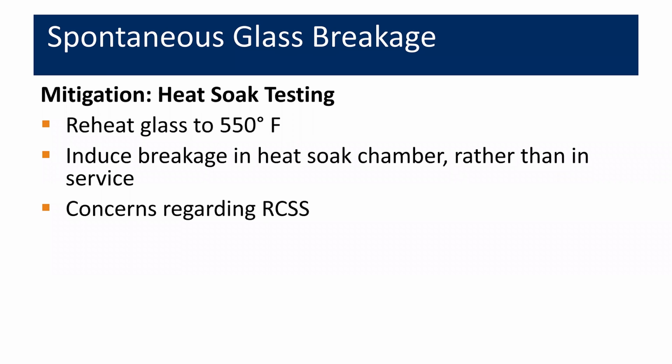Now, there are some that have expressed concerns about the heat soak testing process and that it may relax the beneficial RCSS, or residual compressive surface stress, at the glass surface. However, recent research has indicated that using the typical European process should probably only result in about a few percent reduction of the glass surface stress, relatively insignificant.